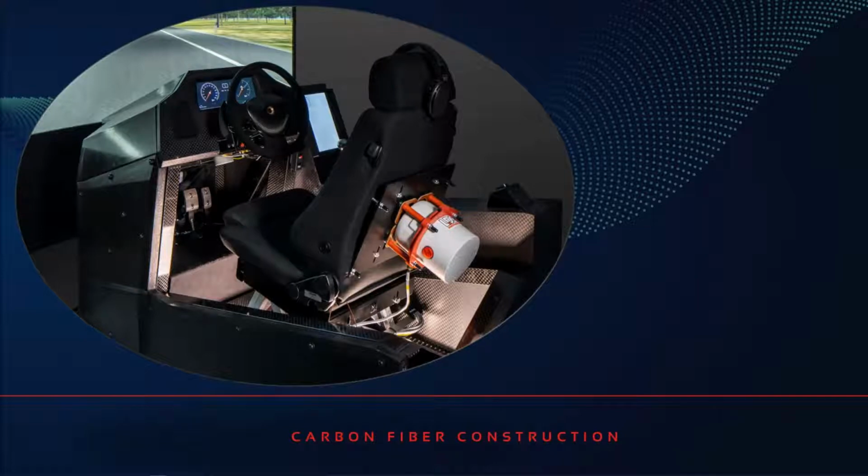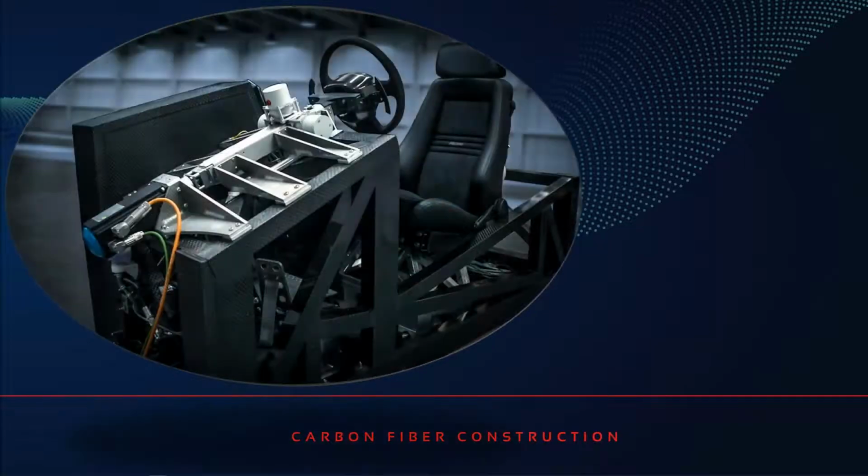The compact NVH simulator utilizes carbon fiber extensively in its construction. The goal was to design a frame with high stiffness that would provide accurate vibration in a relatively lightweight system that would be fairly easy to move. The frame has been designed using simulation and finite element modeling, of course, to be extremely stiff and provide a very stable base for the steering system and steering vibration module. With this structure, it is possible to deliver well-controlled and accurate steering wheel vibration.